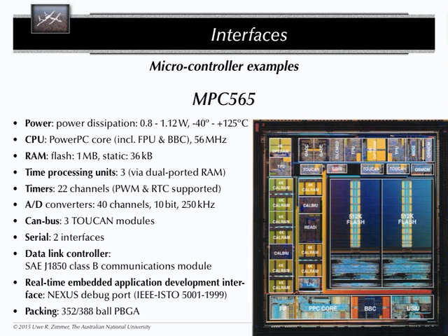This is what dual ported physically means. So that you can read and write from this RAM area without anybody ever noticing any interference from somebody else. So they can both read, they can both write, but they're actually multiplexing. The RAM is only listening half of the time to one device, half of the time to the other device, but it's running so fast that both devices think they're running at full speed.